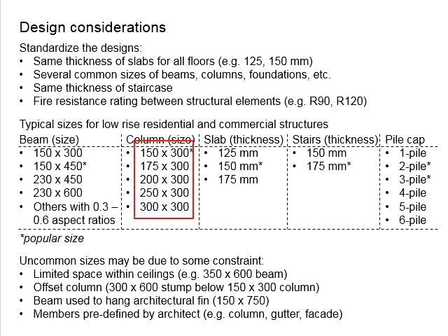These are the typical sizes of the columns. The most common one will be 150 times 300. These are column sizes that are just nicely embedded in the wall. Unless you have insufficient axial capacity, you may need to increase the size of the column. However, beyond 150 mm, let's say 175, it cannot be fully hidden within the wall. You need to be aware of this, and most likely you require the consent of the architect to allow those areas to pop out from the wall.